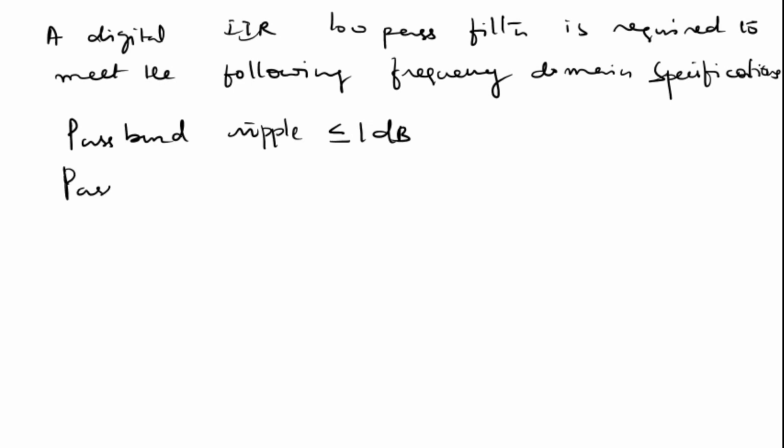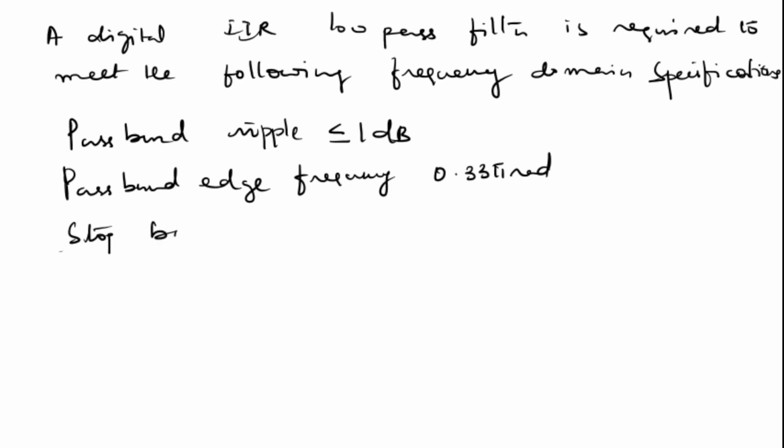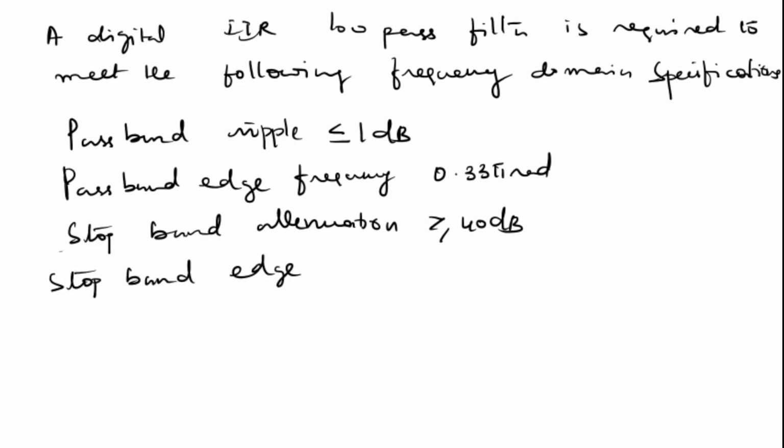Second one, passband edge frequency 0.33π radian. Third one, stop band attenuation greater than or equal to 40 decibel. Fourth one, stop band edge frequency 0.5π radian.